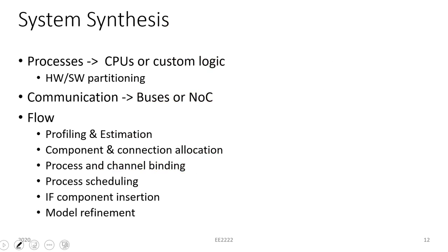When we talk about system synthesis, specifically from a hardware point of view, what we try to do is map processes into logic. So identifying what is going to be the hardware aspect and what is going to be the software aspect, identifying the communication requirements, the necessary communication buses, and things like that. Then we identify all the scheduling requirements and the various components.